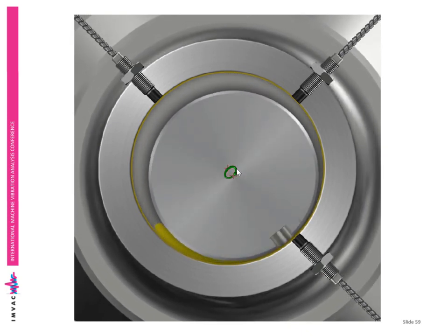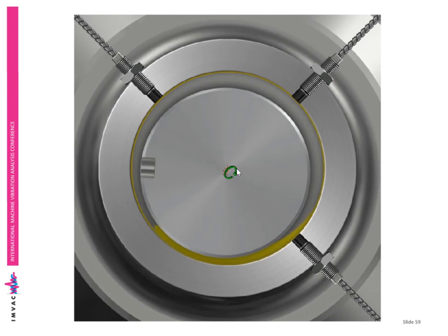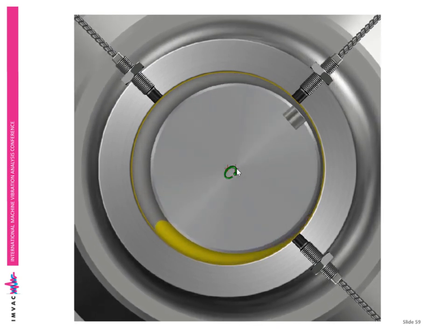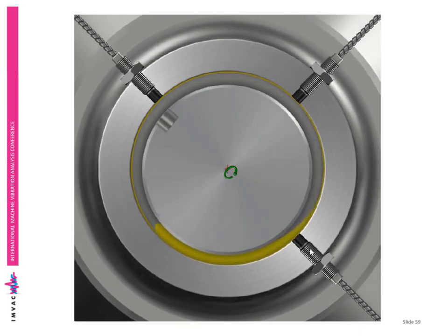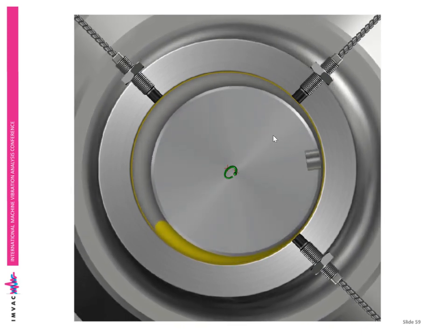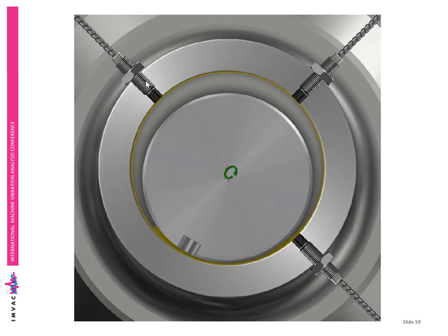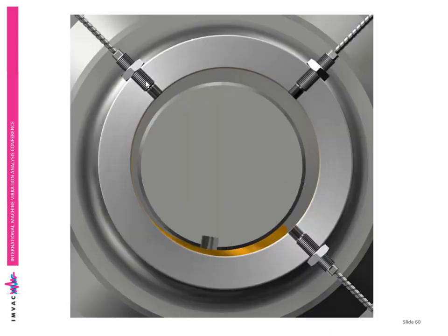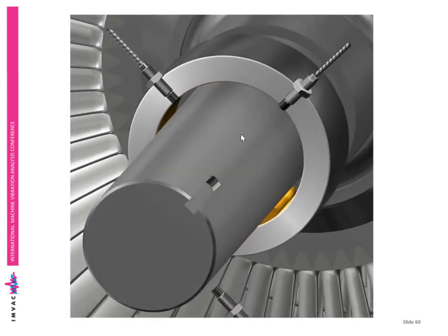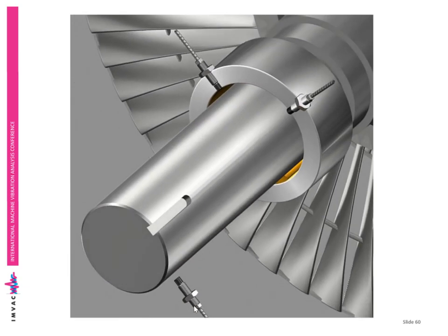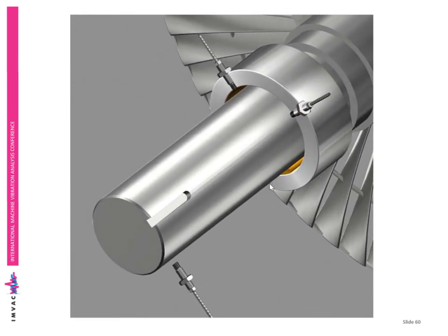Now, at the same time, we need timing information for the sake of the orbit and for phase, and that's what this probe, the keyphasor, is doing. It's seeing the keyway as it rotates around. Now they're not all in the same plane, so let's have a look at that. Okay, now it's rotating in the opposite direction, sorry for the confusion, but in any case, now you can see that this probe is mounted axially in a different location to these probes.